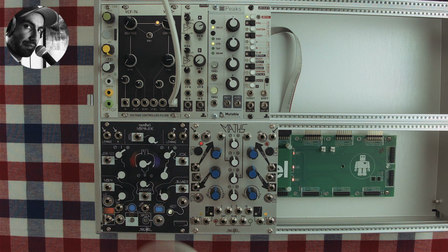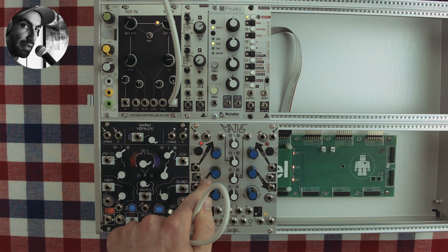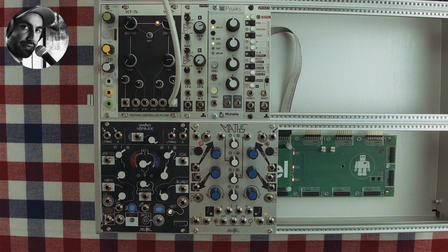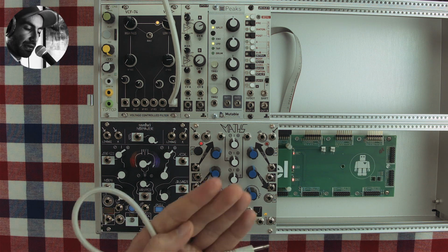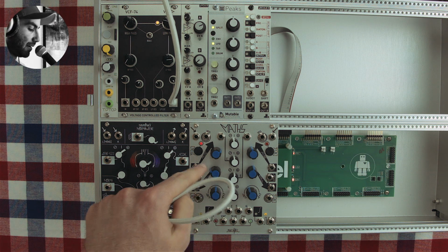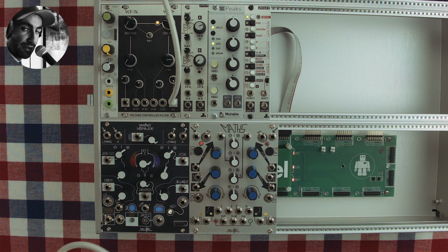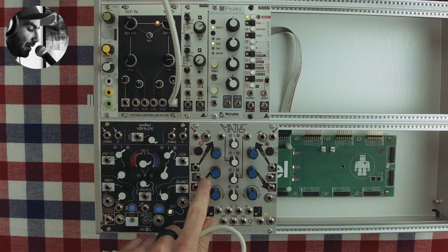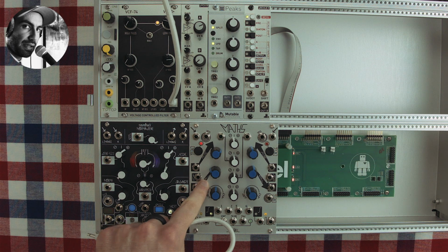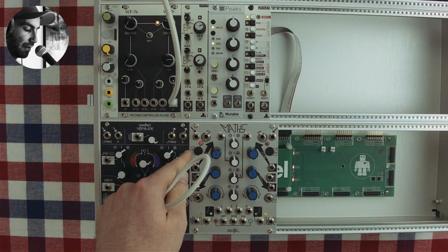And then the way it behaves as an LFO is that the combination of the rise and fall time. So it'll start off at 0 volts. It'll try to make its way to 10 volts. And the duration it'll take to go from 0 to 10 is determined by the rise time. Once it reaches 10 volts, it'll try to go back to 0 volts. And the duration of that is determined by the fall time. And then when it reaches 0 volts, it'll repeat the cycle because the cycle is on here.